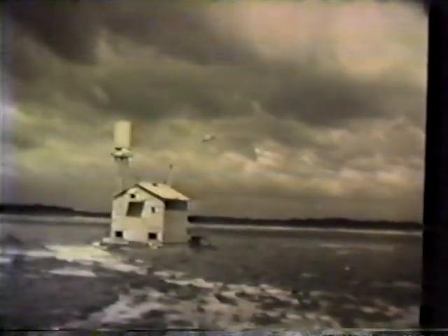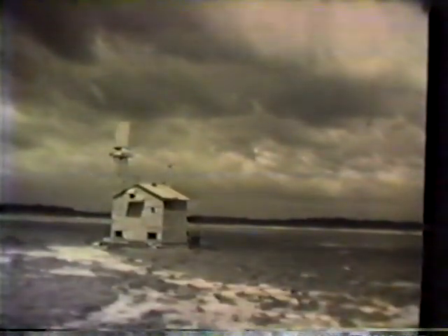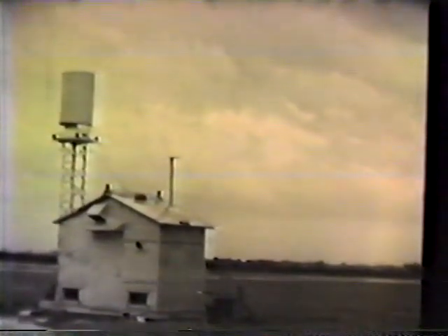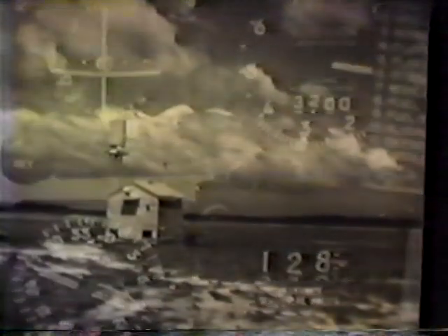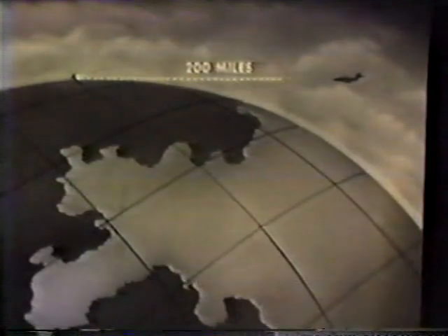Electronic systems for helping aircraft to navigate is called Tacan, short for Tactical Air Navigation. With Tacan, the ground or shipboard component of the system, a beacon, transmits signals that tell a pilot audibly the identity of the beacon and visually the bearing of the beacon and its distance from his aircraft. A beacon is usually unattended. The range is about 200 nautical miles, line of sight.